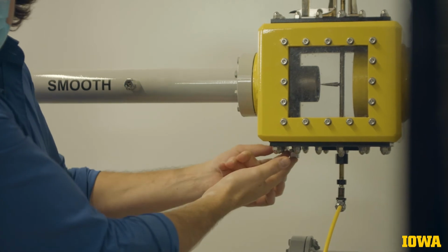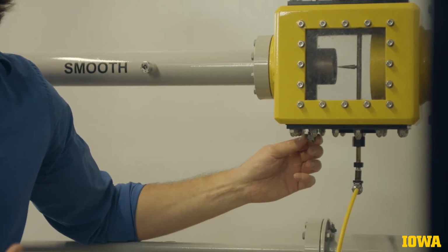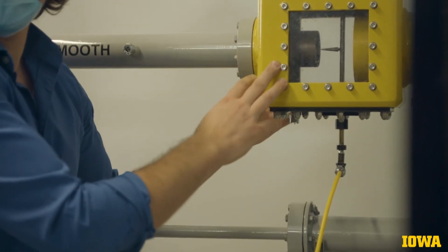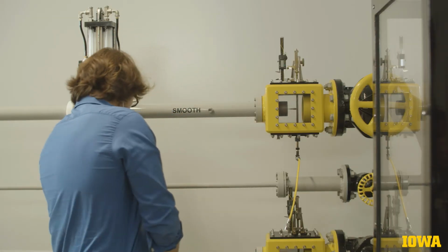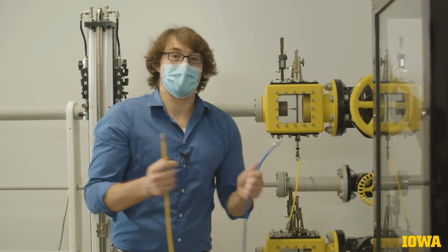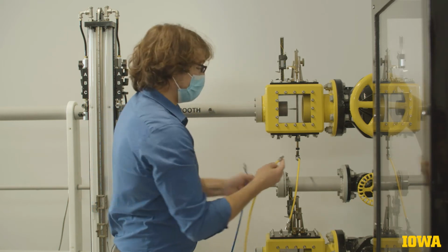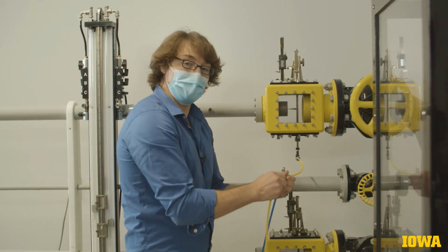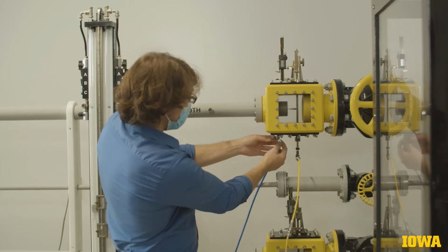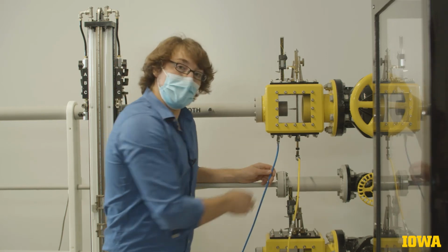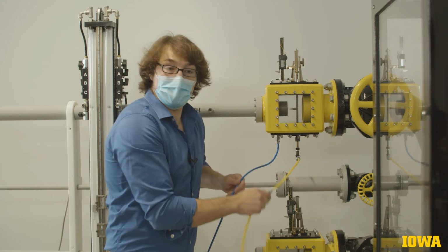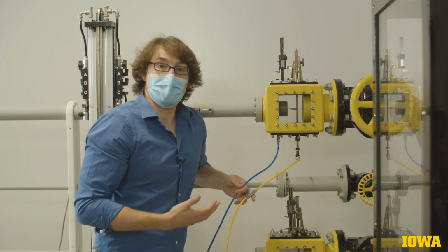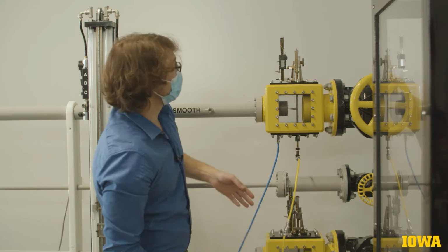On the bottom of the box, we have a second tap, which measures the ambient pressure inside of the box, or what's known as the static pressure. By using the same differential pressure transducer we used in the pipes, connecting the high pressure leg to the stagnation pressure tap and the low pressure leg to the static pressure tap, we'll be able to obtain the difference between those two pressures, which is then proportional to the velocity squared.